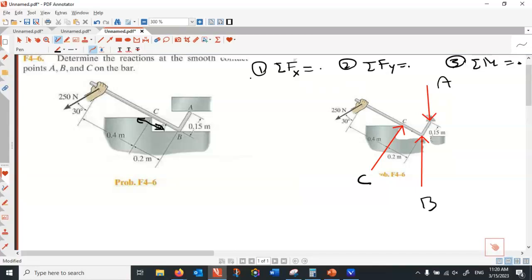All right, I think if we take the forces in the x direction, that's my x, and this is my y direction. If I take the forces in x, the only forces in x are the 250 component and the C component, right? So that is solvable. That would be minus 200. That's equation number one, condition number one. That is 250 Newton projected horizontally.